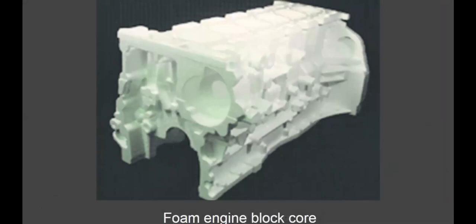This is the piece of material that is used for casting the engine. In the casting process, they actually pour molten aluminum or molten iron into a casting. This foam fills the area of the casting where the molten aluminum or molten iron will take shape. As you pour the molten iron, this foam burns away, and then as the molten iron solidifies, this is the shape that it takes.